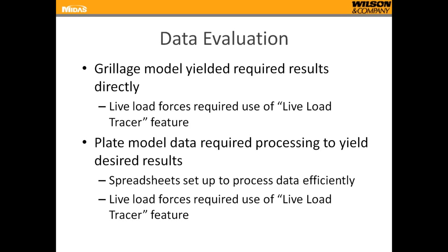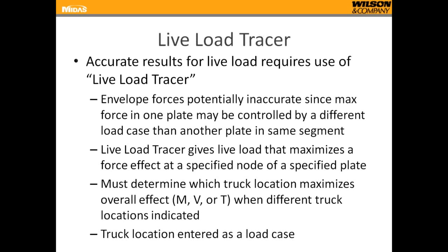When you're considering shear, you want to use the same truck location that's giving you the maximum shear to get you the moment at that section when you're using the modified compression theory to calculate your shear resistance. The plate model data required processing to yield the desired results.